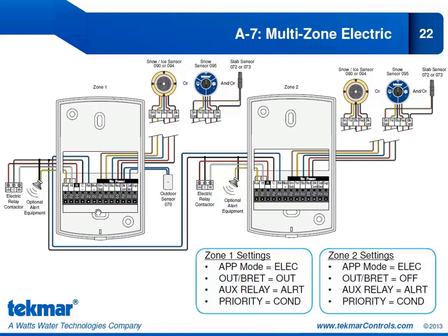So we go back and forth by allowing only one heat relay of any zone on at any given time. And we do that to avoid large instantaneous electrical demands on our system and the associated large surplus charges from our electric utility when that happens. So this conditional priority setting for electric applications is a real benefit to using the 654 for these types of applications.